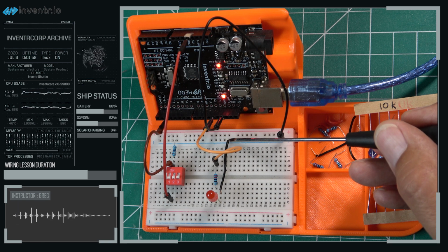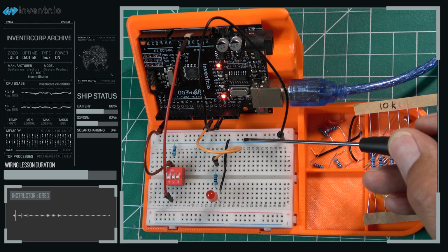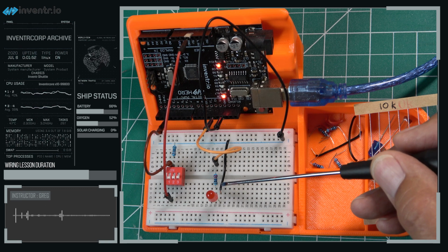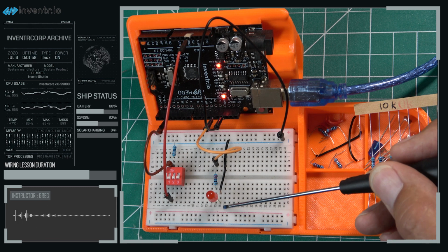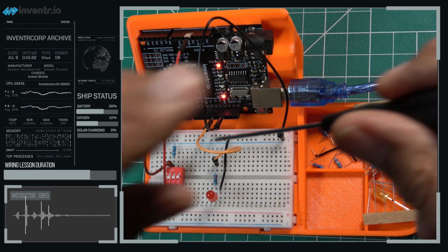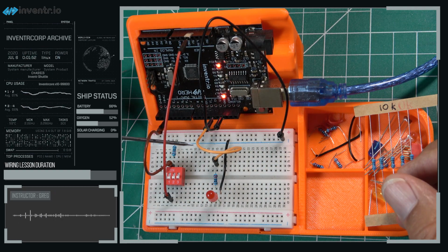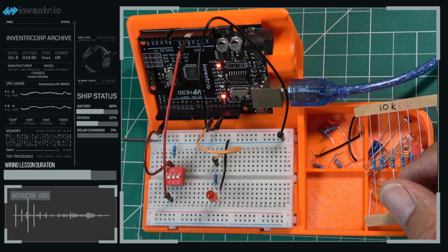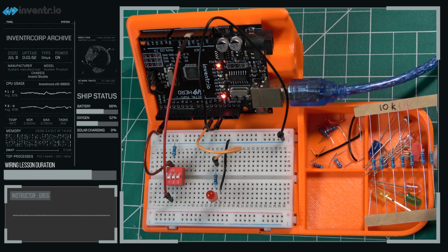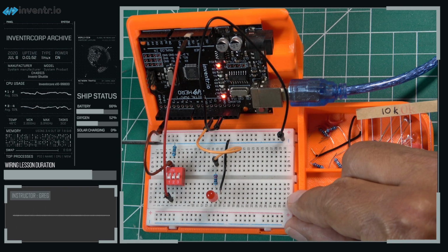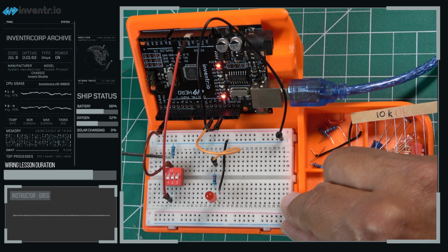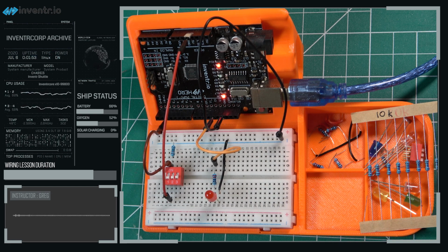We have a black wire connecting from this ground line to the lower end, the low side of our LED. So this is the ground side of the LED. And we're also using the same ground line right here to connect to the bottom side, the low voltage side of our logic resistor that's being used to provide a signal to go to pin 2.